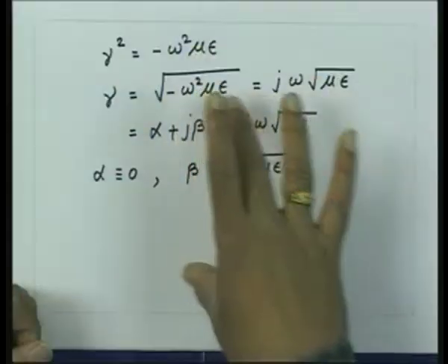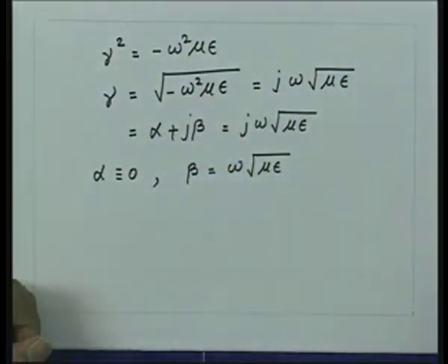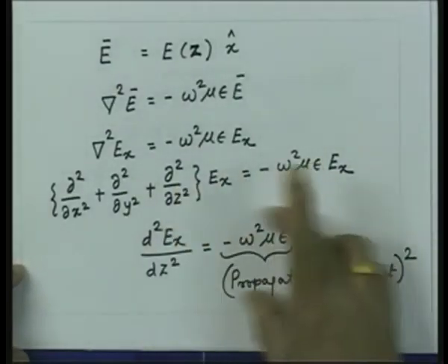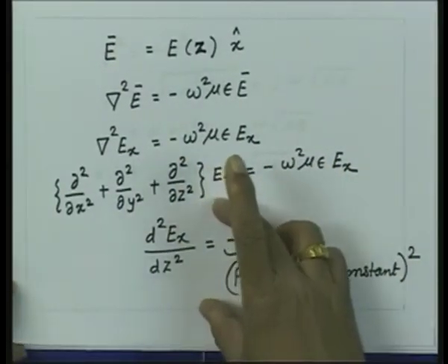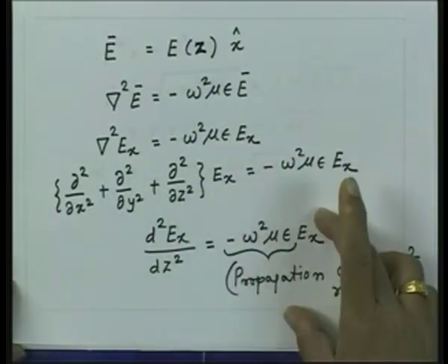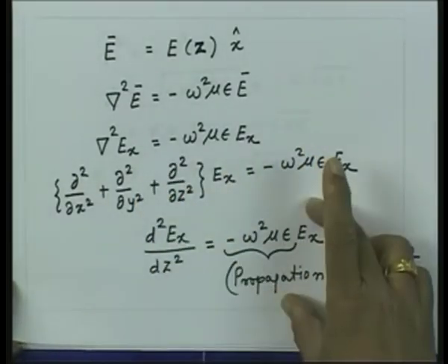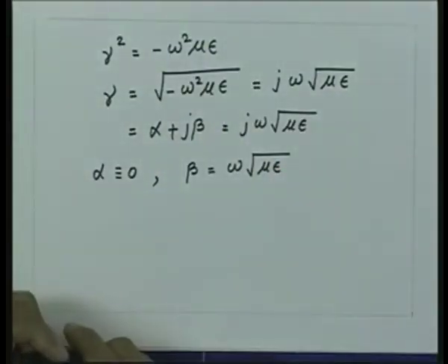Precisely the same thing should be represented here: the solution for Ex will be wave-like, and its amplitude should not vary as a function of distance in the direction z. So, in terms of the terminology we have developed, this would represent lossless propagation on a transmission line.